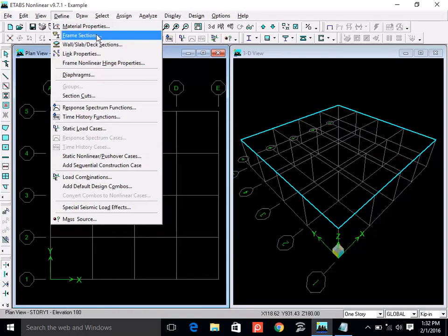So you have to think, and I'll take you back to PRC1. In a 9-inch wide beam, you can accommodate hardly 3 steel bars. You have to maintain a distance between the steel bars.